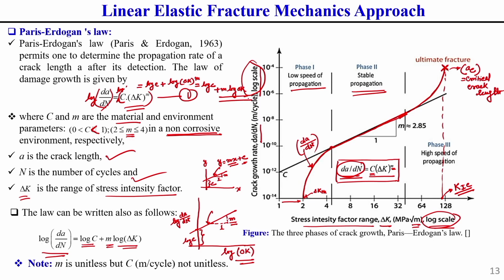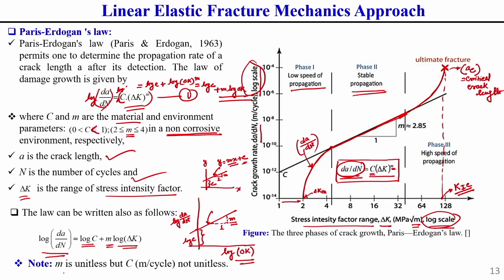Okay. So, in the next lecture I will discuss in more detail the linear elastic fracture mechanics approach. There also I will solve some problems on this approach. Here, always keep in mind that whatever M you get, M is unitless, but C has a unit. The unit of C is generally meter per cycle, which is not a unitless quantity. You should keep this in mind. Okay. So, in the next lecture I will start from here. Thank you.